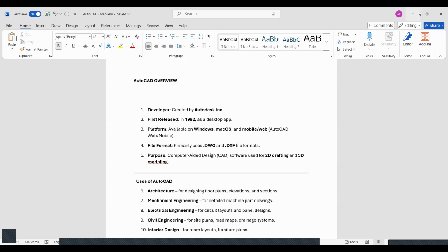Now what I do, I go to quick select, then I go to circles, then I go to color by yellow. Only the yellow part will be selected. But if I do quick select, going here, then color by red, only red color gets selected. If I do it as multiple, then everything which is red gets selected.